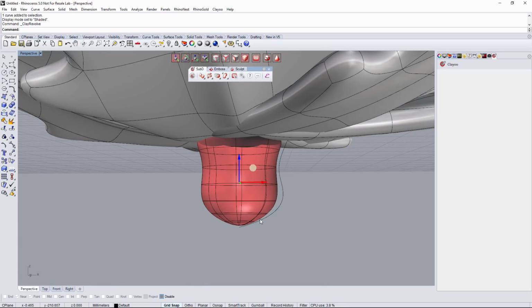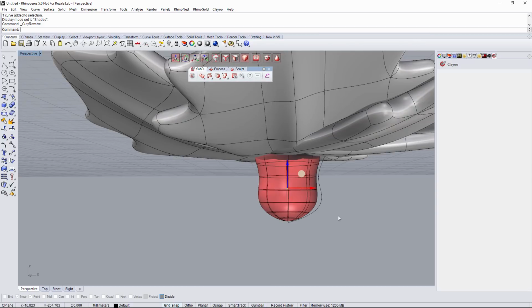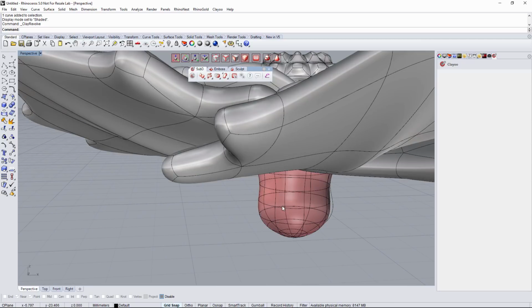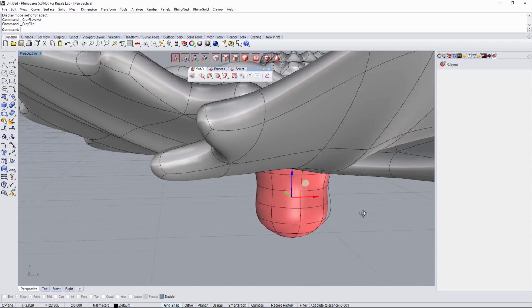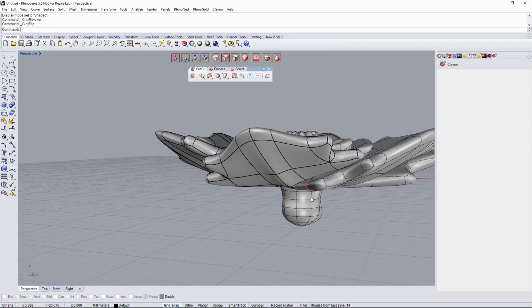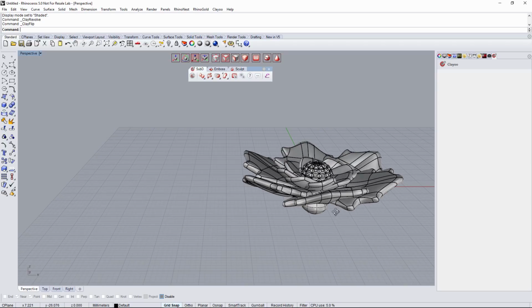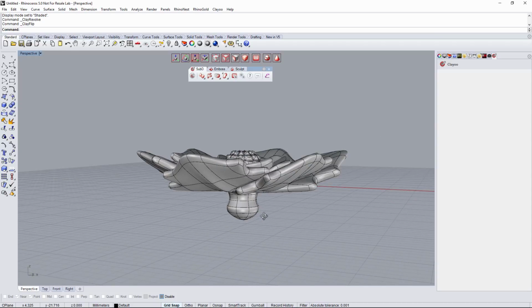In this case, now the normals turned flipped. Okay, I thought that this point was touching the 0, 0 axis, so I capped it, but no problem. Now you can see that it looks like it's flipped, so I can just select it, going for edition and flip normals. So right now we have the model correctly displayed. So in here, what I'm going to do, I'm going to grab some edges in case that I want to refine a little bit the shape. So just refining a little bit till we get this effect like that. It's going to be nice.